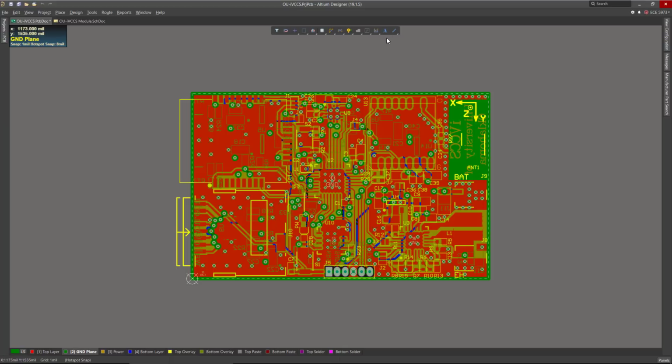So basically the active bar provides point and click access to the commonly used commands and actions related to the document in focus. This is called contextual, meaning it will display commands according to which document has the focus. By default, when starting a design document, the active bar will appear at the upper border of the focused document. And this active bar is customizable in Altium Designer, and we will see that later on.